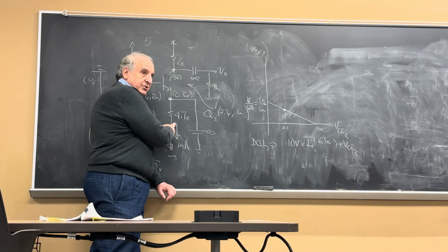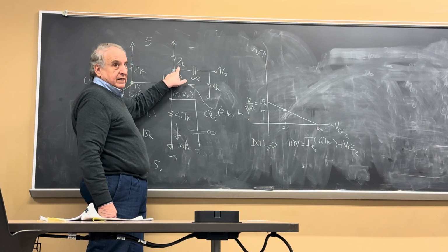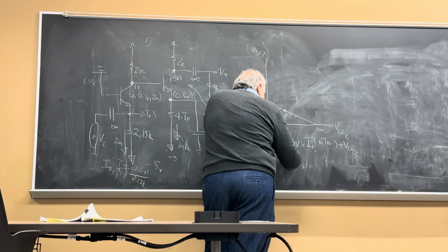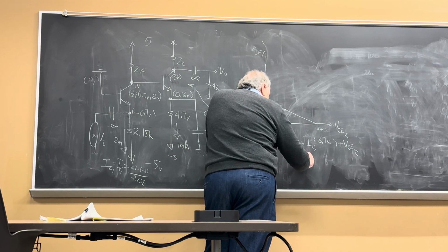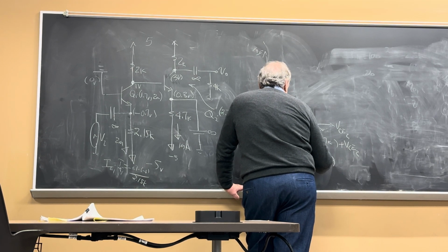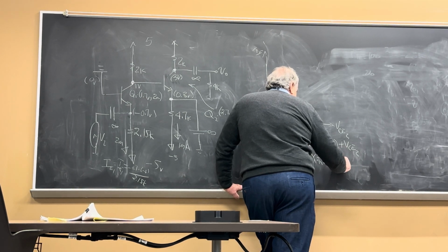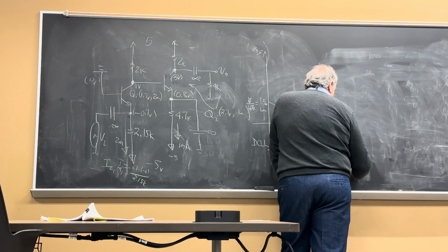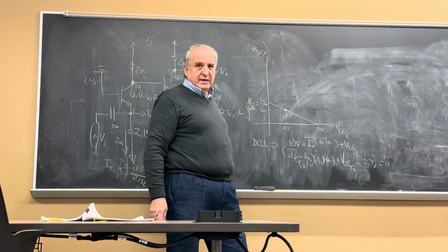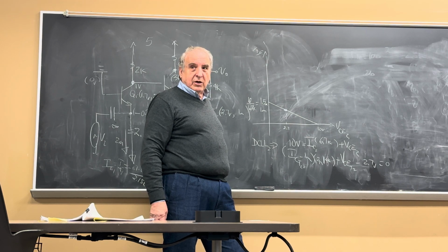What happens to this resistor? Shorts. This is dead. 4K in parallel with 4K becomes 1, right? So the AC load line is going to be IC total 2 minus 1 milliamp times the impedance across, which will be 2K in parallel with 4K plus VCE total 2 minus 2.7 volt equals 0. Everybody understands where this comes from, right? From the AC equation, do you know?